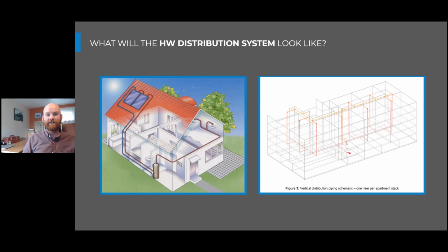So now if we have a central hot water plant, regardless of what it is, if it's a heat pump or a gas water heater, we might now have a 3-inch or a 4-inch main carrying hot water down level 1 of the corridor, and then risers that go up to serve multiple units are connected on top with another maybe 1.5-inch hot water circulation main, and then that's piped back down to our central heat plant.